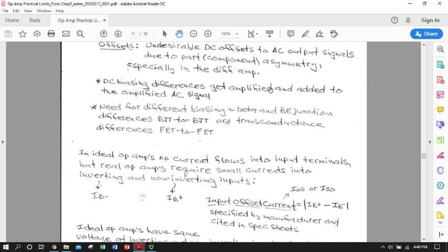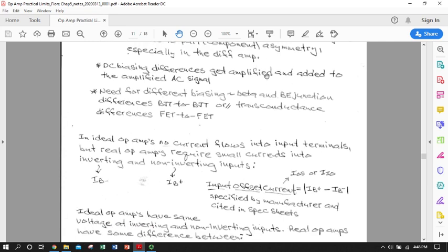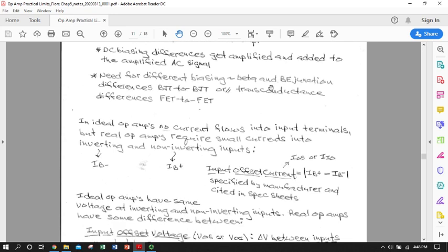And I believe in the first lab we went over measuring things like our input offset currents and our output offset voltages, getting an idea of what that symmetry was and what its consequences were on our voltage output, which is what we care about from an amplifier. It's the output voltage. That's why we're amplifying it in the first place. We want a bigger output.